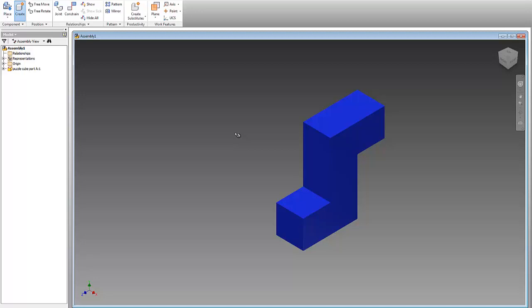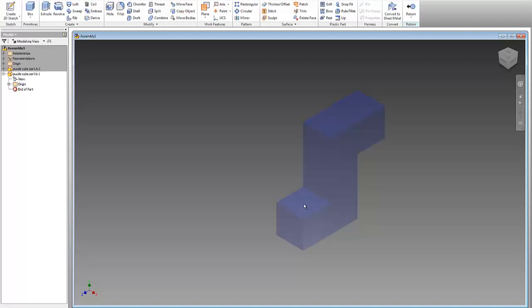what surface do we want to use as an XYZ location to work with? And typically we'll choose a surface on the existing part. And so I'll choose this. I can choose either the top surface or the side surface, depending upon how we're going to create the part. I'll choose the top surface here. So what it's doing is it just selected that as my common surface. It hasn't put a sketch on it yet. I need to put a sketch on this surface. It just said that that's the surface that the relationship is going to be based on.